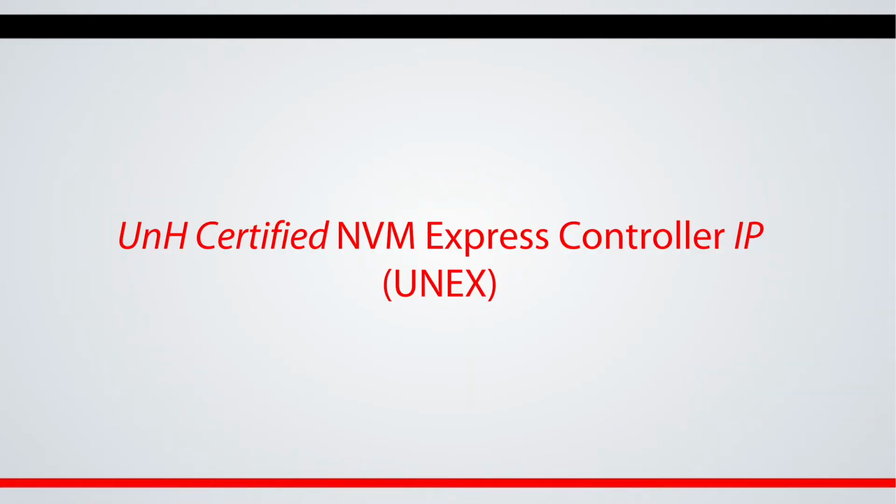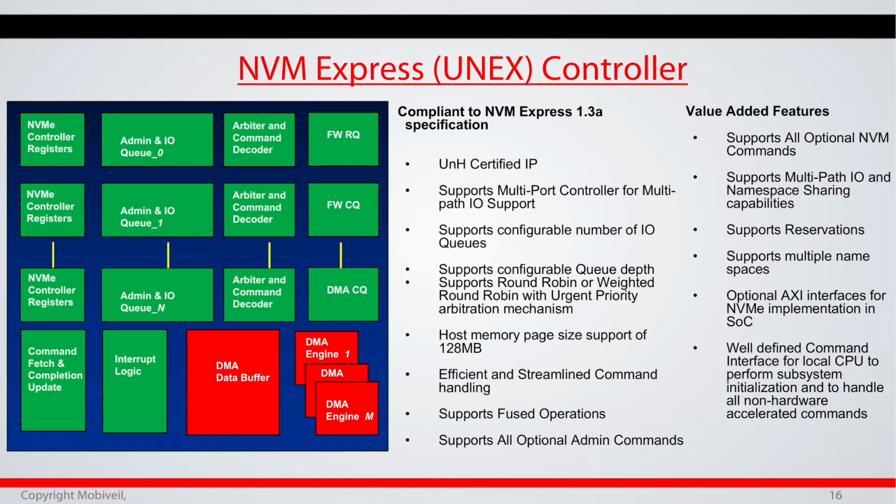And then NVMe Express, what we call NVMe UNEX, Universal NVMe Express Controller. It's compliant with 1.3a, the latest NVMe Express specification. This is UNH certified IP. What it means is that it's a standard, and the solution needs to be compliant and interoperable, certified by a standard body. For NVMe, if anybody is doing an NVMe-based SSD today, they need to get it certified at UNH. This IP is standalone, certified by UNH.